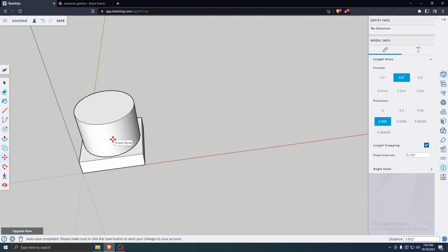So any line you can hover over where approximately the middle is, and it will just snap to the midpoint. Once it snaps, go to the other midpoint, hover, no clicking, move the mouse to the middle of the square. If you're following a nice straight line, you'll get to a point where it's snapping to both midpoints. So now I want another box shape on top of this, and instead of drawing a whole new box shape,